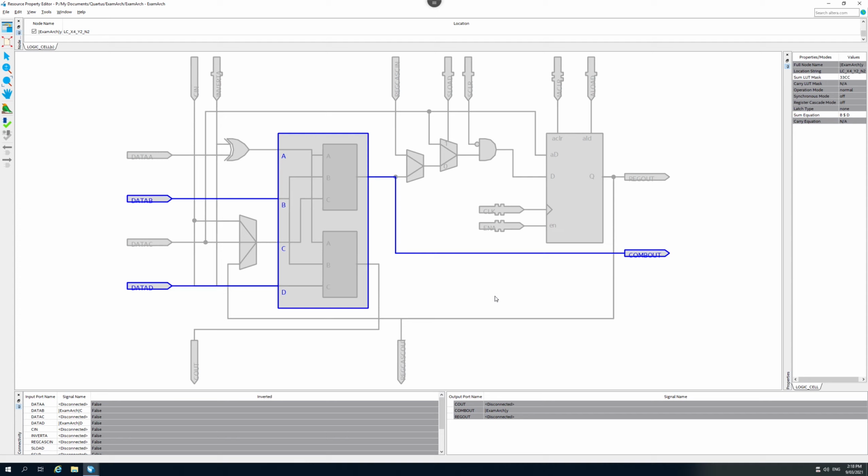And the main principle is simply that we have here in blue a lookup table, and we have over here a flip-flop. And every logic element on any FPGA is going to contain a lookup table and a flip-flop. Those are the core ingredients. The other circuitry has got to do with different FPGA manufacturers wanting to try to make their chips faster than their competitors. The Altera chips are set up to be able to do fast addition.